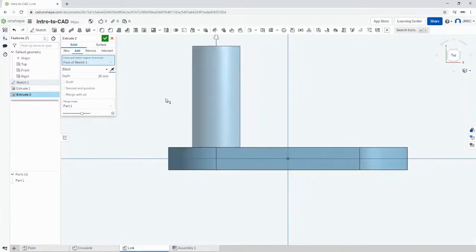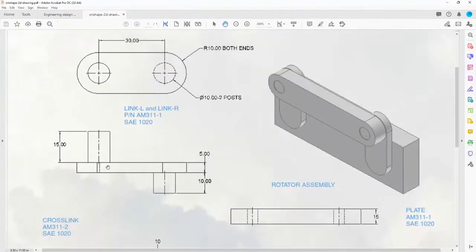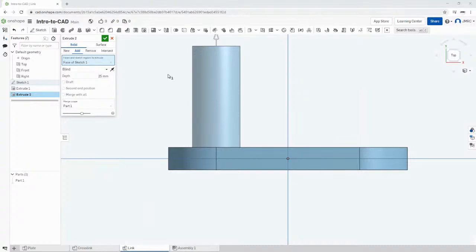And notice our extrusion is coming all the way at the middle or center. Okay, so with that in mind, instead of keying in 15, we are extruding at this plane or line at the middle. So we need to consider adding 2.5 to that as well. And in Onshape, we can do mathematical operations in the dialog boxes. So I'm going to type in